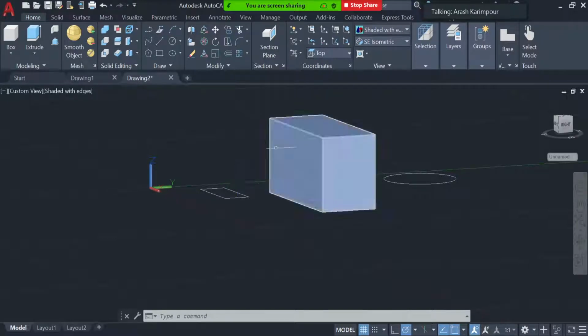So what if I want to draw something, for example, vertically? What if I want to draw something on a slanted surface? At the moment, my XY axis is the horizontal plane, which goes through 0, 0, 0. So everything I draw in 2D is going to stick to that plane, no matter where I draw it, no matter how hard I try to draw it anywhere else.